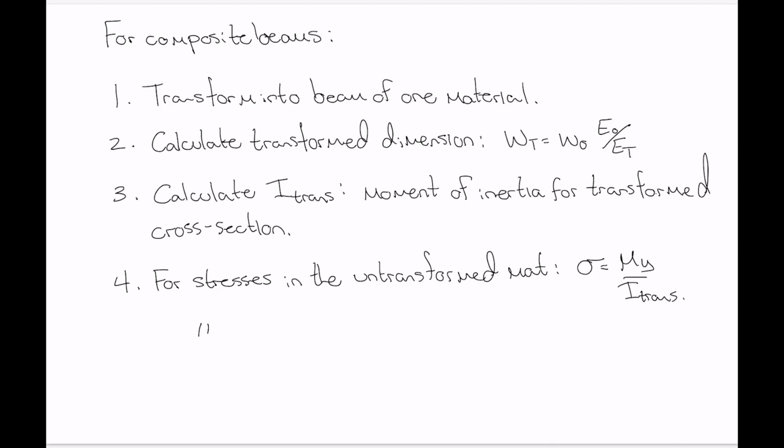And for stresses in the transformed material, we do the same thing, but we have to remember to multiply the result by the ratio of the moduli of elasticity of the two materials. So, My over I transformed.